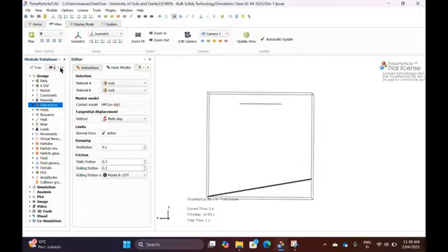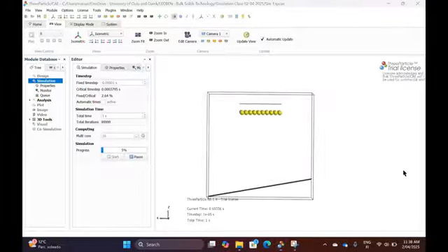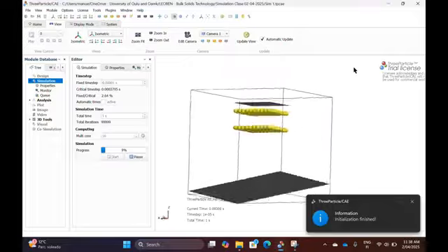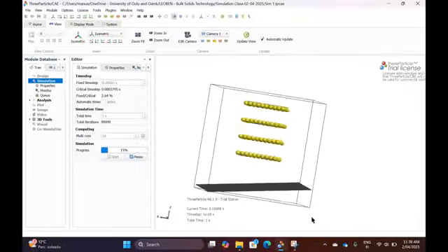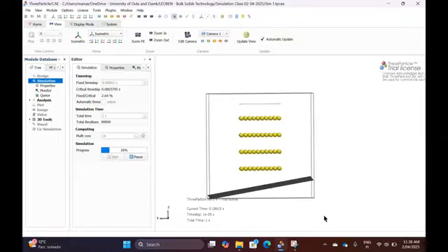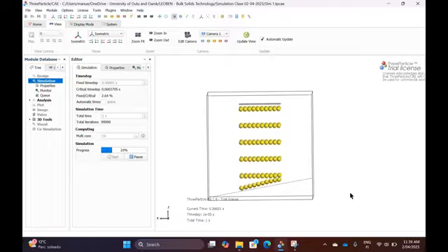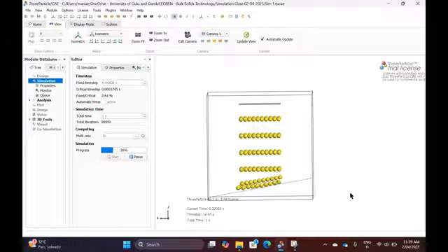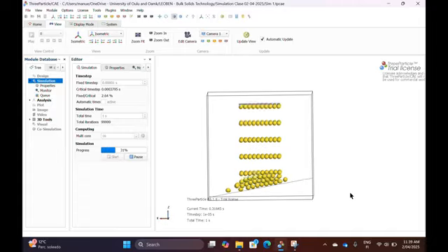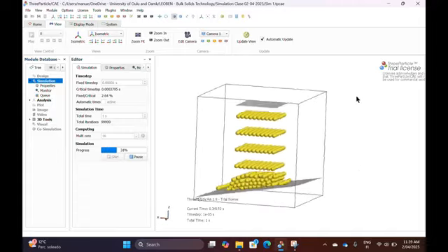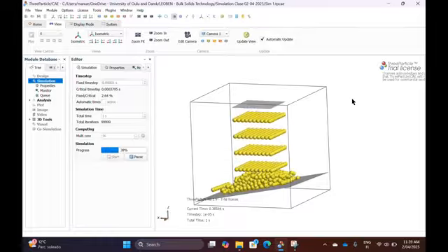Before I start now, it's really slow, not really what I want. You can see here 2.64%. It doesn't say that much to you, but probably you remember from the lecture, there was a time step that was critical, the Rayleigh time step. It was like this shock wave going through a solid particle. If you have a very rigid particle, a very small particle, you need a small time step. The program automatically computes in the background a time step that is suitable. And 20% of the time step is a good value to start with. So I changed my time step to about 20%.